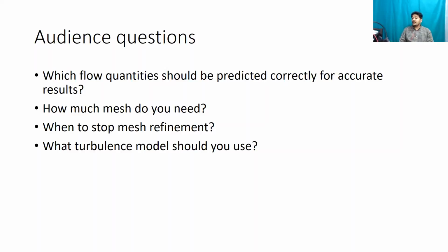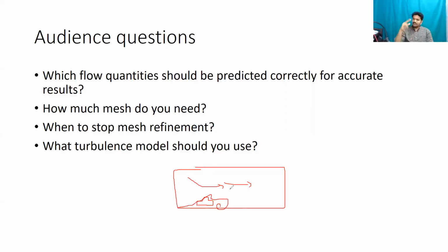or are you talking about the entire velocity distribution? The entire, exactly right. And for simplification, we can basically split the flow regime whenever there's an external aerodynamics. So for example, say that you have a small car like this, you can basically split that into two regions, right? So all the aerodynamic activities that happen, they actually happen inside boundary layers, correct? Inside boundary layers and outside the boundary layers. So these are the two regions that you can think of that exist in your problem.